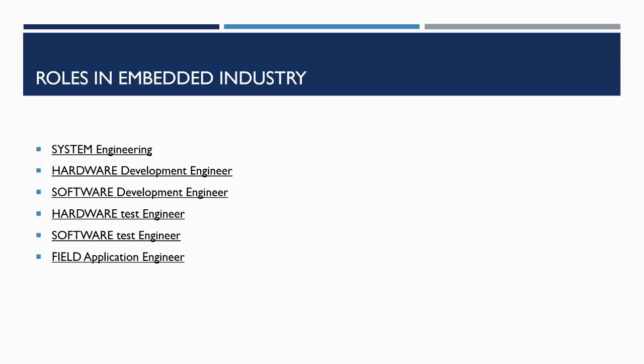Now when they go to the advanced category, they should be very good at handling 8-bit, 16-bit and 32-bit microcontrollers, and the tools they require. Suppose I am going for an 8-bit microcontroller, there should be a microcontroller related IDE, integrated development environment. For example, if I am going to use an 8051 microcontroller, the IDE is Keil MicroVision. Using this Keil MicroVision IDE, one can write the software and simulate.